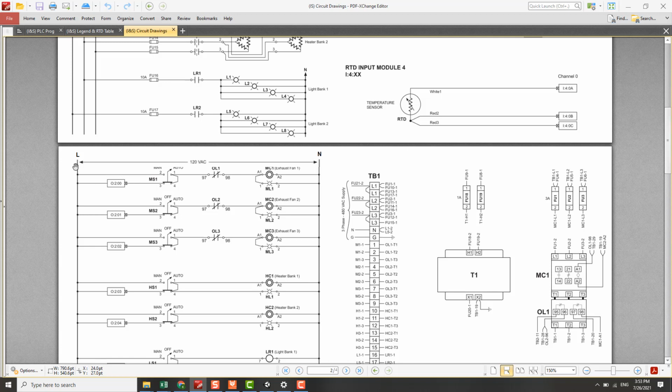Okay, when the AC current flows through to source the PLC output switch module 2 channel 0, it will sync to the motor selector 1, auxiliary switch overload relay 1, and then this external load of motor fan, exhaust fan motor contactor coil 1 and the motor lighting 1 to the ground or to the neutral.